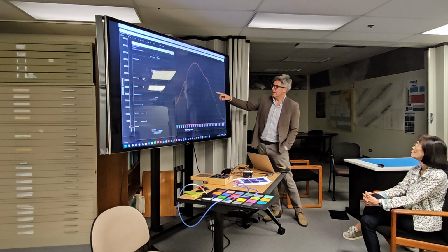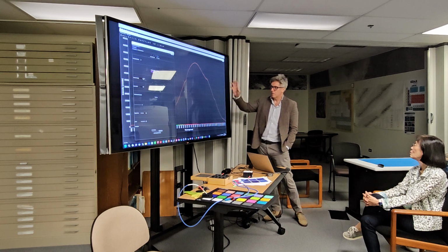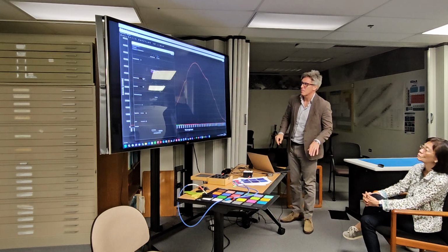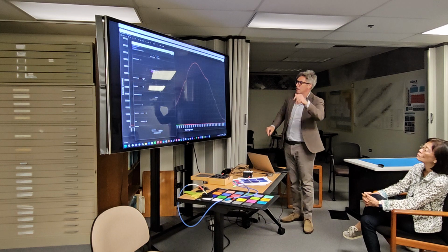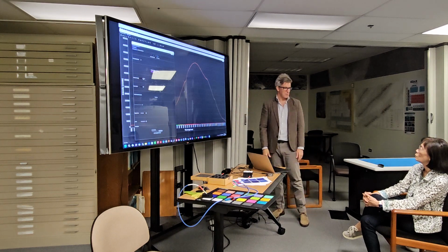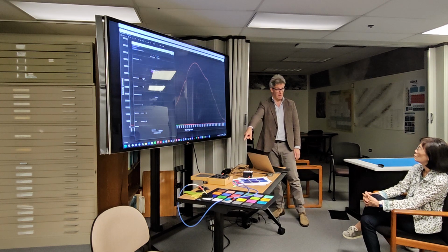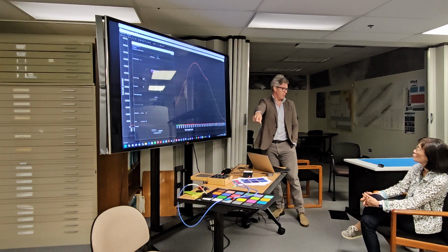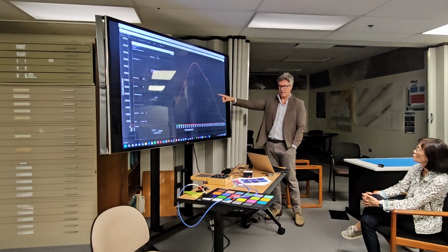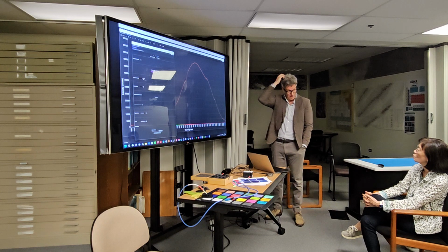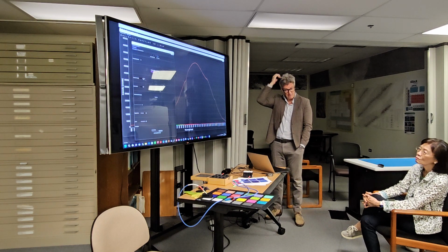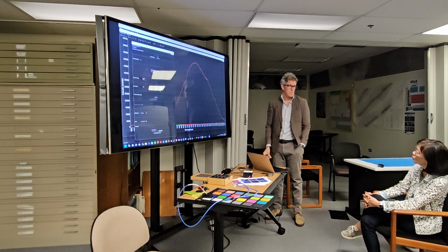Now, in that case, they have a bit more time. So you'll see here, this is running at that integration time of 120 milliseconds. What do you notice about this curve? Is it stable or is it flickering? Is it changing? Flickering, right. And that is stable because I paid a couple $1,000 for it. That's not changing, right, because I put it in my metal block. So what are we seeing here? What is this flickering from the spectrometer? It's just the inherent noise in the spectrometer.